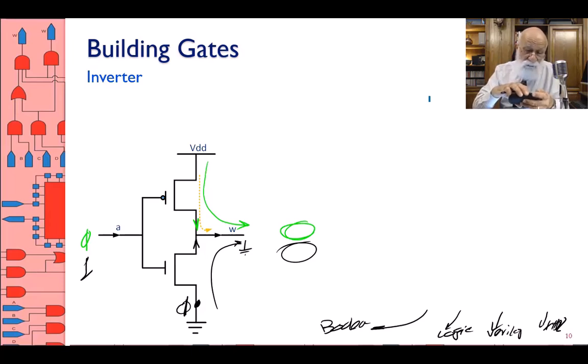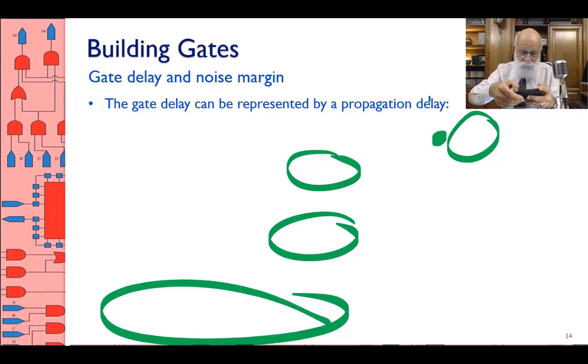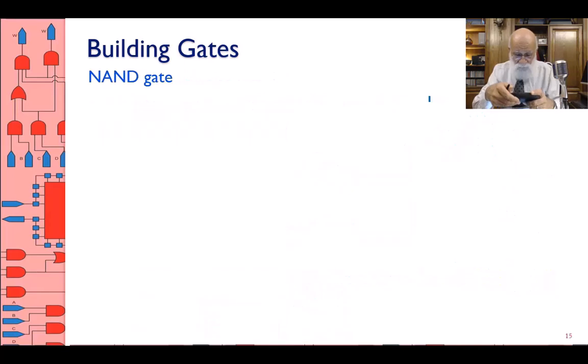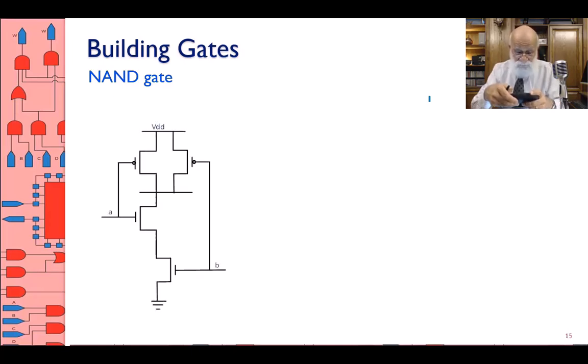And with those other gates, we are not going to go into a lot of the details of the timing, meaning that since we already understand the inverter, it has a pull-up transistor, it has a single pull-down transistor, and it is very easily analyzable using basic current flow through the PMOS, through the NMOS.